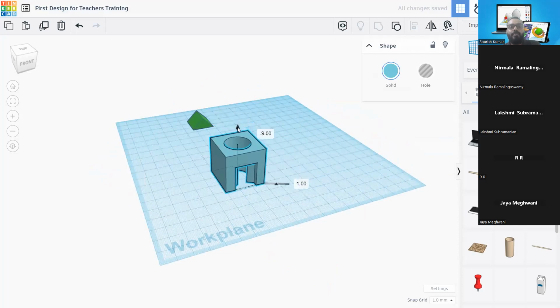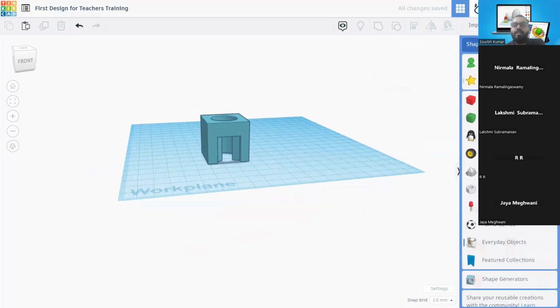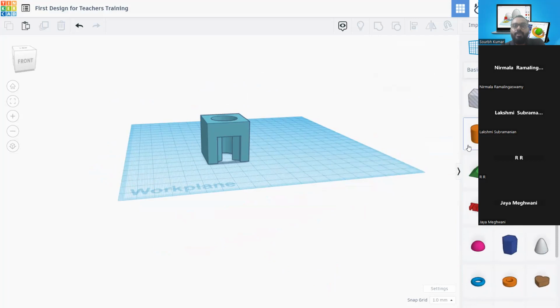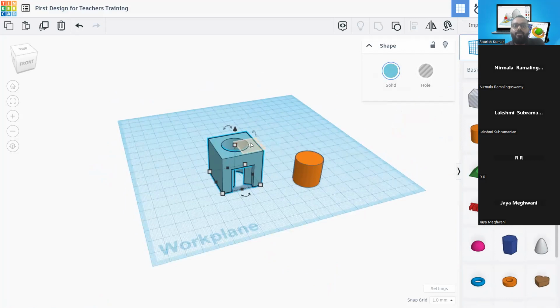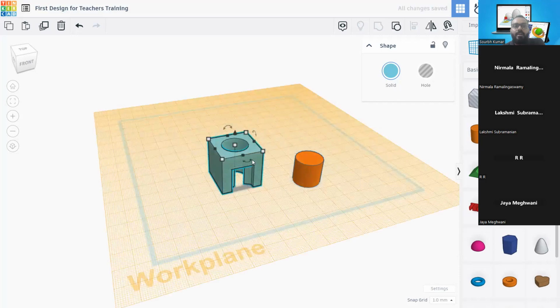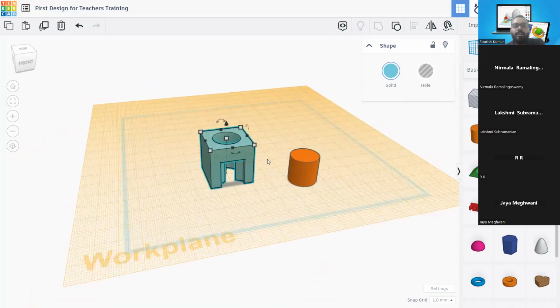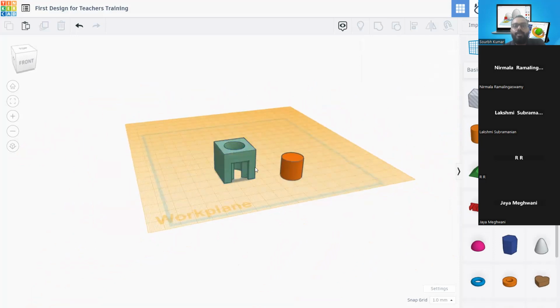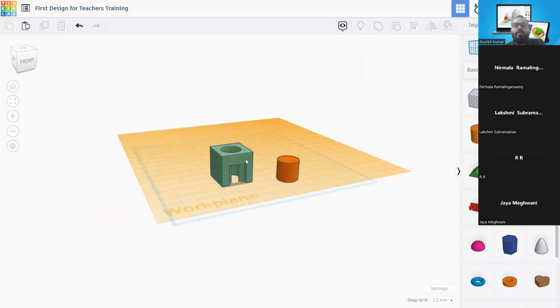So now I'm dragging and dropping an object onto the workplane. Suppose by any chance you cannot place this slender object on top of these, and you have to face that limitation. So we do have the workplane tool as well. Just click on this object and the workplane tool, and just dragging and dropping the workplane on this one will give you a range to have the workplane on this one. The other workplane we just created is for other components to be placed on top of it.